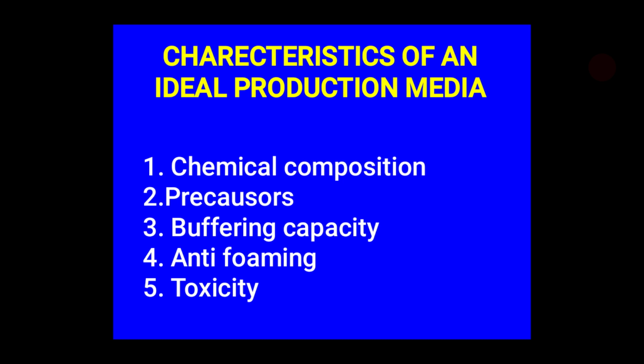Okay, because foaming is a serious problem in the fermentation industry, since it may aid in contaminating the fermentation media and possibly may cause other problems in the fermentation. So hence we have to add anti-foaming agents. One example I will tell you is lard oil, which is mixed with octadecanol for the penicillin fermentation. So this will avoid what? Foaming.